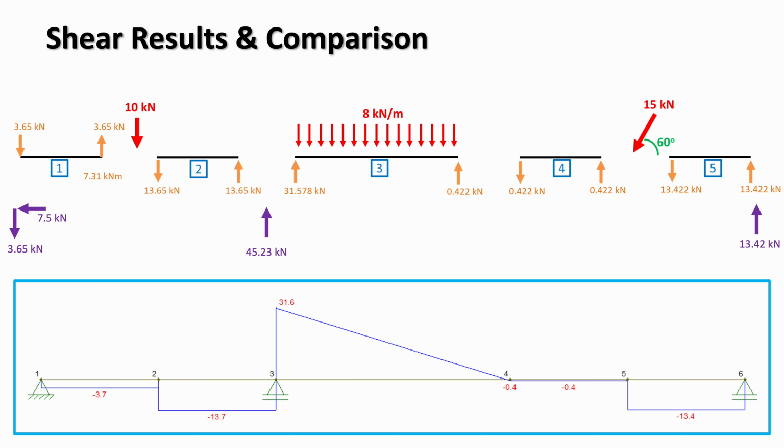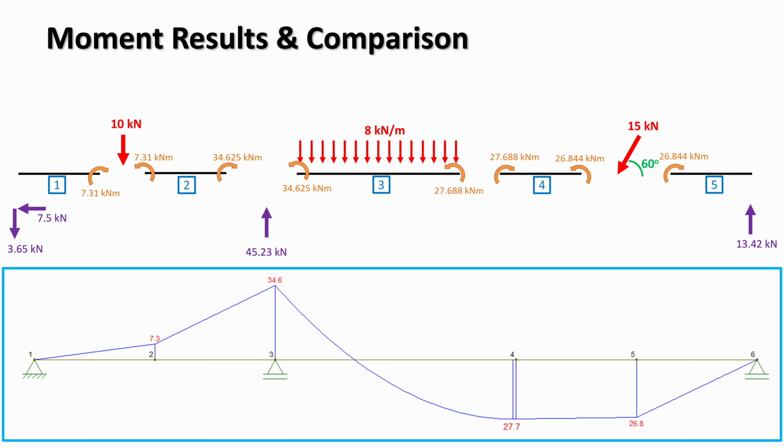And on this slide, we're looking at the bending moments from the stiffness method code and comparing them with a moment diagram from F-tool. The values at the top are the interpretation of the moments from our MATLAB results, once again drawn in their true physical sense. Any negative values have been flipped, so the arrows show the actual bending behavior. As before, the slide only shows moment, so the external loads and reactions are included, but the structure is not in full equilibrium without shear forces.